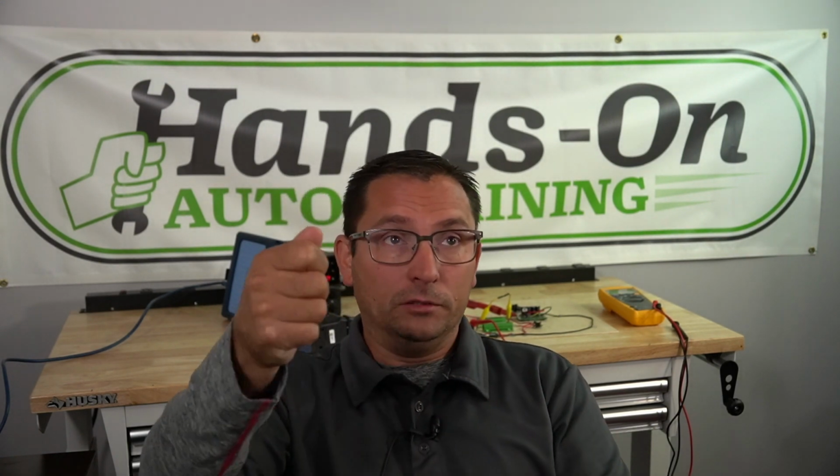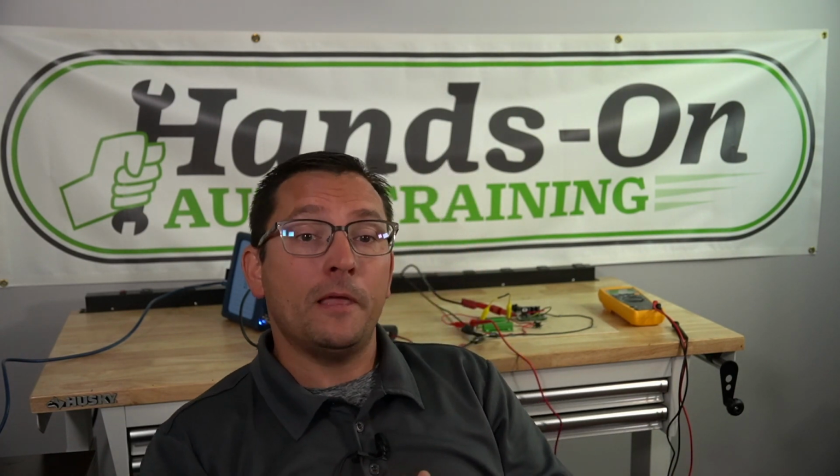Now at this point, for those of you that like to load circuits, and we talk back and forth about test lights and all that stuff, I don't actually have a physical test light that has the lead or the probe and all that stuff. I do carry some 194 bulbs and some other bulbs if I really need to load something up. I usually like to let the load be the load, but in this instance, we saw a difference in voltage between one power input and another, so I was like, well, with my lead stuck in here, let me go ahead and add a little bit more of a load.